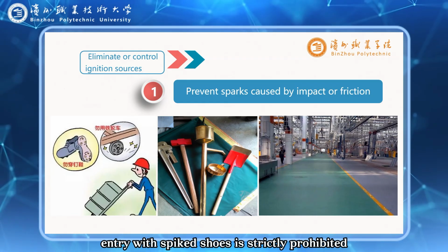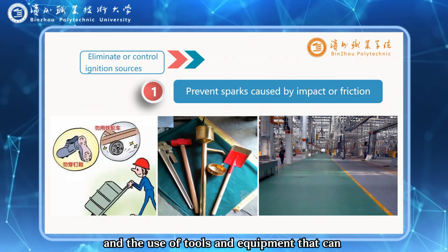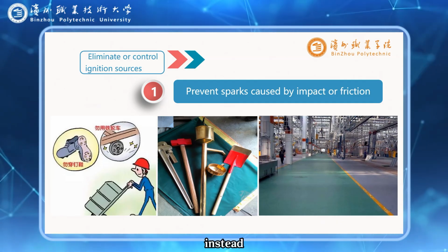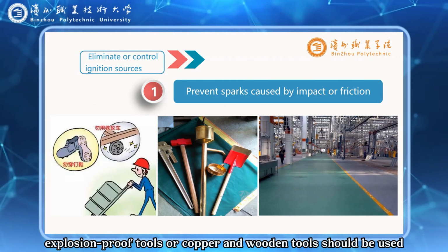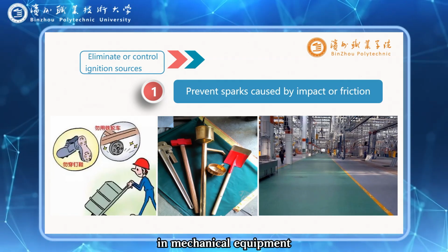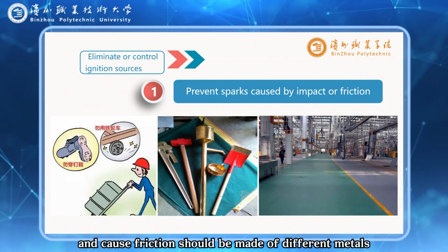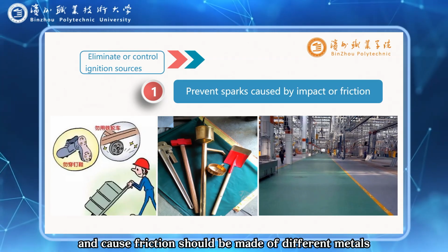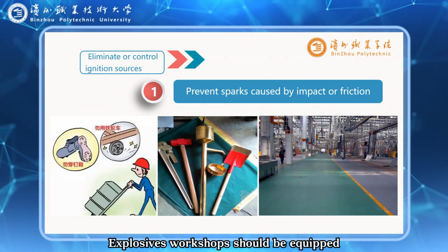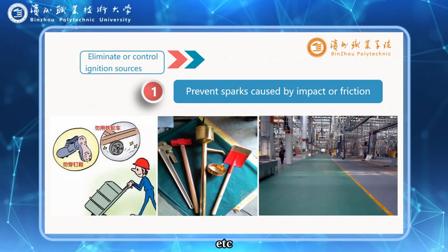For example, entry with spiked shoes is strictly prohibited, and the use of tools and equipment that can generate impact sparks is strictly prohibited. Instead, explosion-proof tools or copper and wooden tools should be used. Additionally, in mechanical equipment, any two parts that may come into contact and cause friction should be made of different metals, such as steel and copper, or steel and aluminum. Explosives workshops should be equipped with non-sparking flooring, etc.